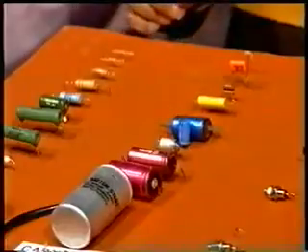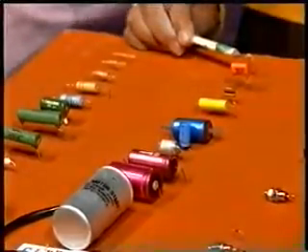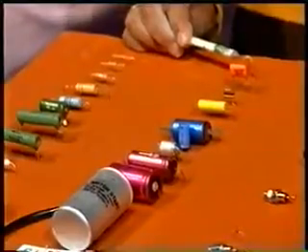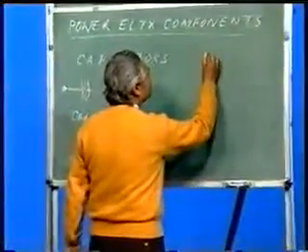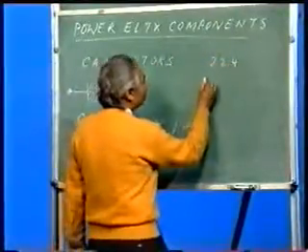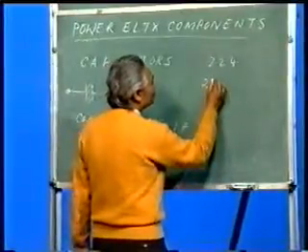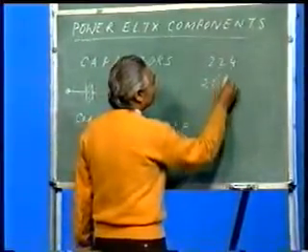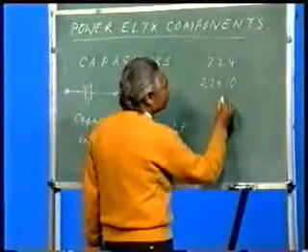There is a trick to know the values. Now if you see this one, which is a disc type ceramic capacitor, there is a figure written on it, 224. Let us see what this 224 is. I will write 2, then the second figure is also 2, and this 4, the third figure, is the multiplier, raised to the power of 10.